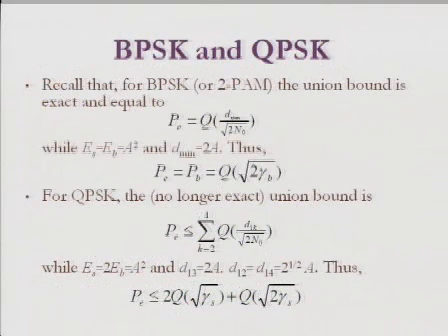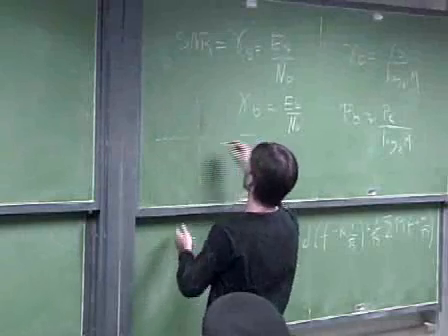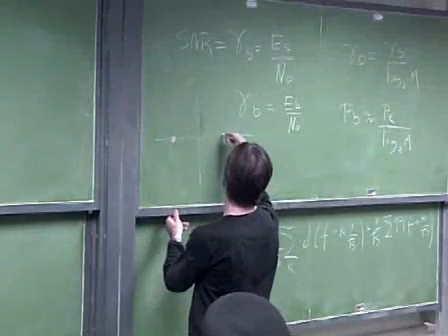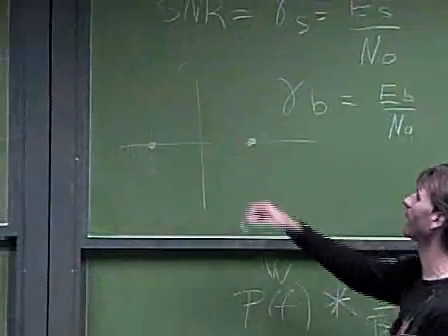Okay, so let's keep these notions handy because we'll be using all of them. Let's start by studying the simplest possible constellation, which is BPSK. This constellation just has 2 points, so it doesn't get any smaller than that. We have 1 point here and 1 point here. This is called BPSK, for binary PSK. It has 2 phases, 0 or pi.